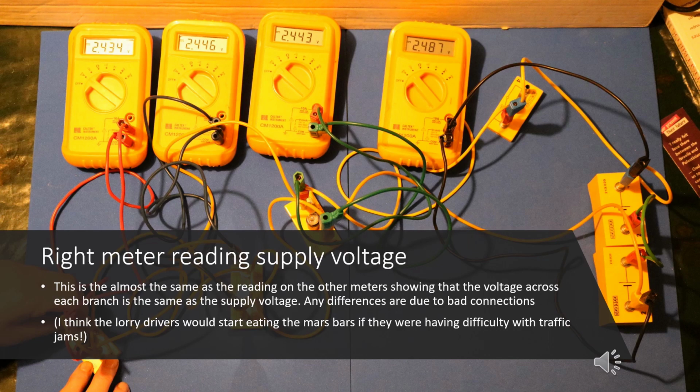And if we look across each bulb, we have 2.443, 2.446 volts, 2.434 volts. Now I know you think, well, that's not exactly the same. And my argument would be that there are some pretty poor connections in the wires. And if we think about that in terms of our model to try and explain it, what we'd say is like some of the lorry drivers are really having trouble getting through the snow and traffic jams on their route, so they're probably going to nibble a few Mars bars on the way.